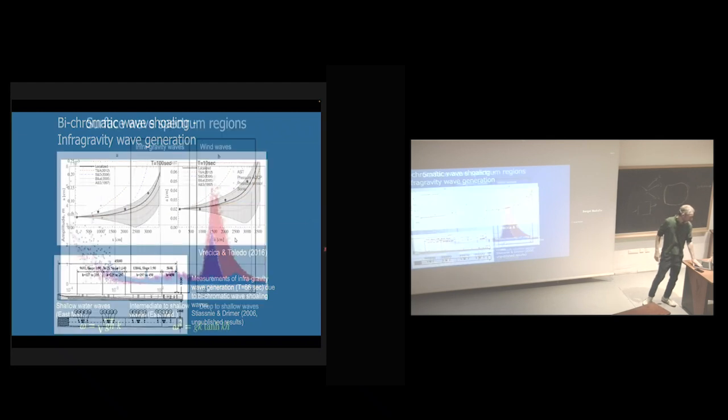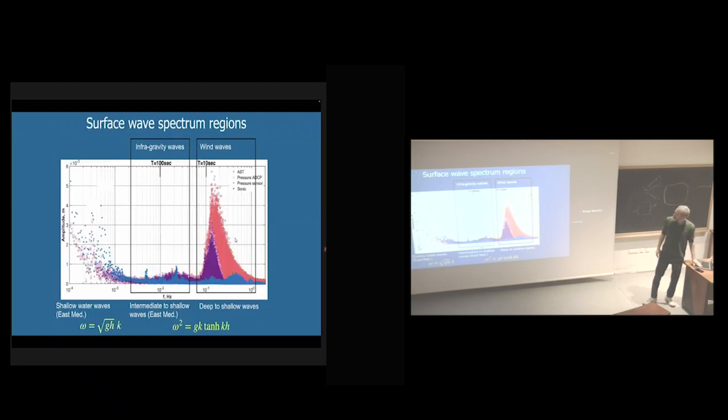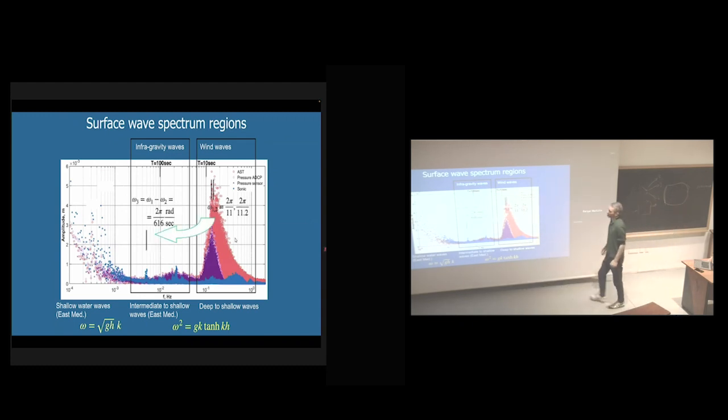Okay, so how will it be in measurements, this thing? If we look at these 2 waves in the measurements, we can point to this 11-second and 11.2-second wave, and poof, they transfer energy to the difference, which is a 616-second wave. It's, I guess, a bit out of the infragravity that we measure. But what you see here, and that's interesting, that's within the port.